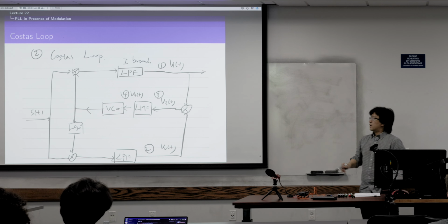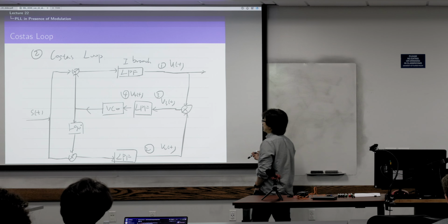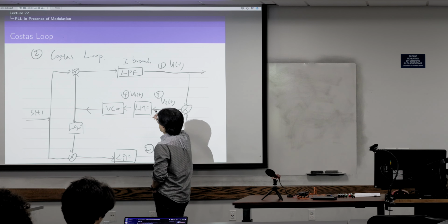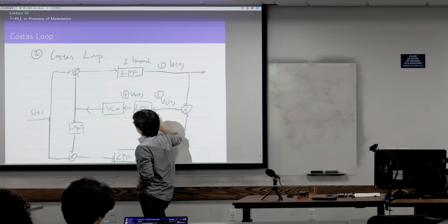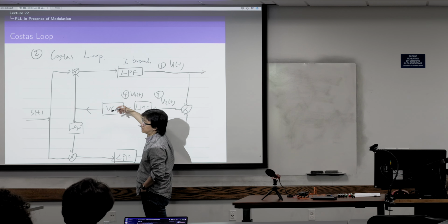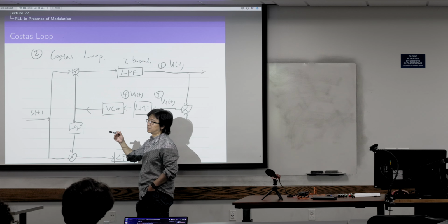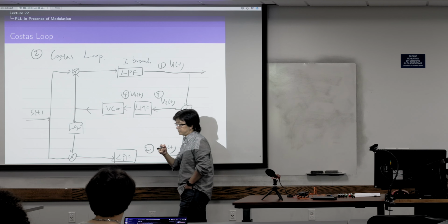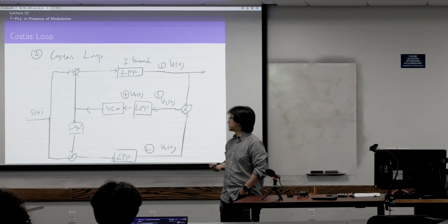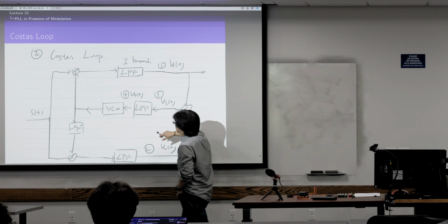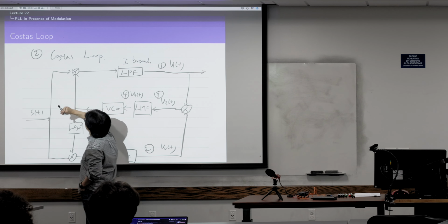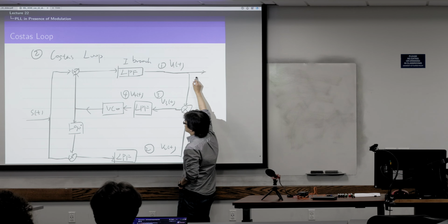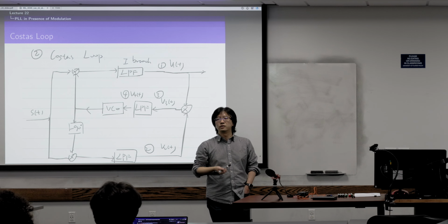Okay, and so this is a Costas loop, and you can see that it's very similar. Again, we did the analysis in class. So basically, after all this procedure here, right? What we can get here is an error, and then after the VCO, which is kind of an integrator, right? From here we can get the signal that we're supposed to get, and then with this multiplier we can get a coherent demodulation, and here is where we can get the desired demodulated signal.